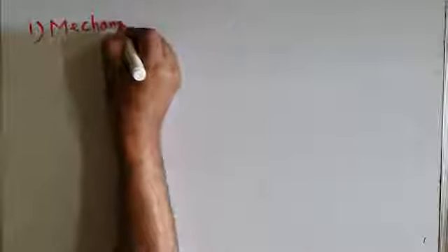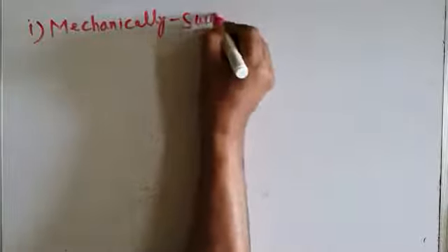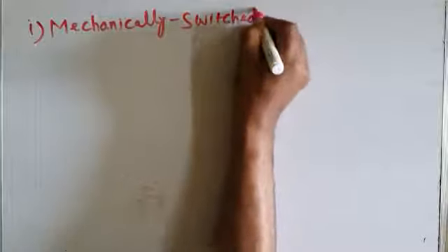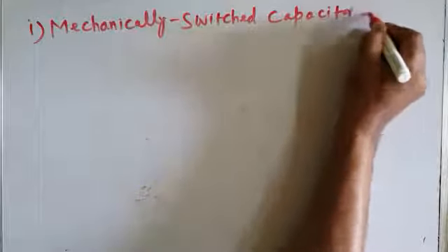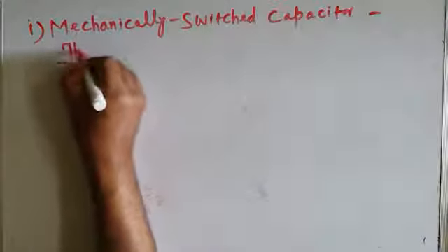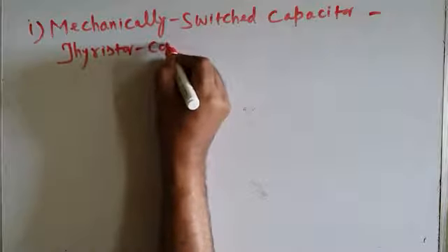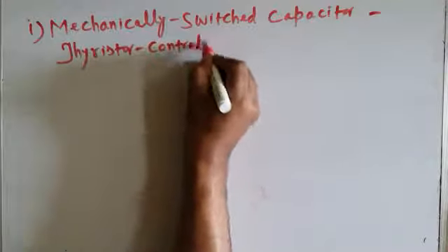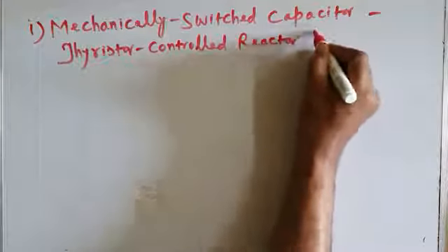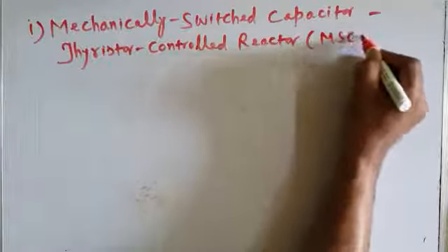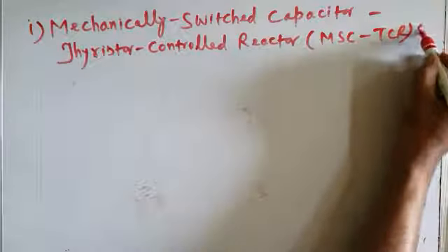And the SVC where the capacitor bank is mechanically switched, I will write here: mechanically switched capacitor dash thyristor controlled reactor, that is MSC-TCR SVC.